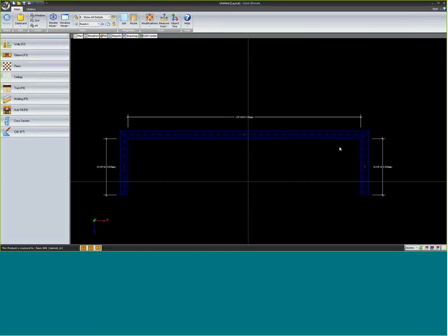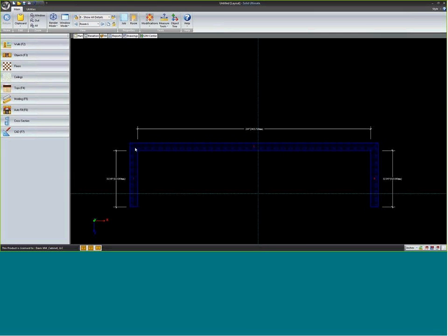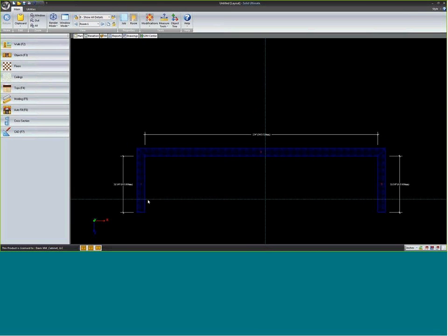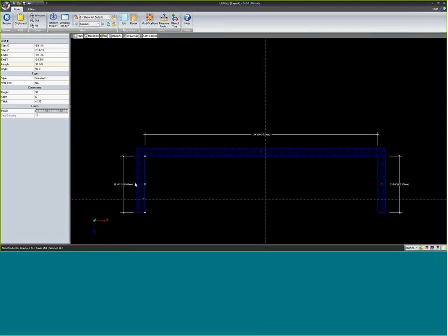Wall sizing. Notice that these walls are all joined together. They show miter joints. Most of the time, if I resize a wall, those joints will stay connected. Every once in a while, you'll move something in a way that Cabinet Vision doesn't understand what you were trying to do, and it will break one of those joints. So you'll have to just play with that. You just have to get a feel for it.